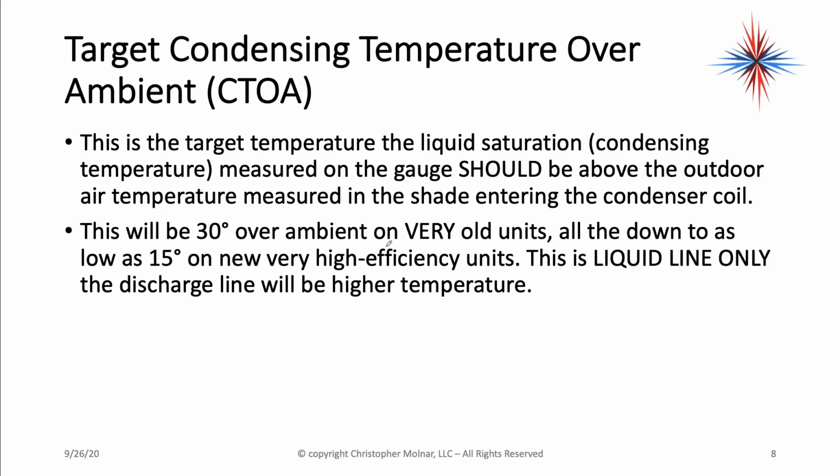The discharge line will be much higher temperatures. So be careful on where you take this. You want to take this on the liquid line right as it is exiting the unit.